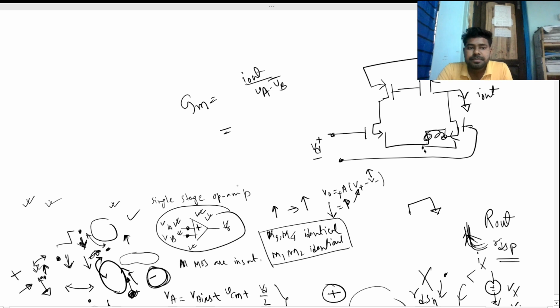What should be the value? And this is our open circuit. We can see that the impedance looking here is 1 over GM3, and we know that this is a small resistance and we have a short circuit path. Then what will be the impedance here? This will be 0, right? So we do an approximation. These two impedances are almost the same, very small, and we assume these two are the same. So we can treat it as a symmetric circuit, right?